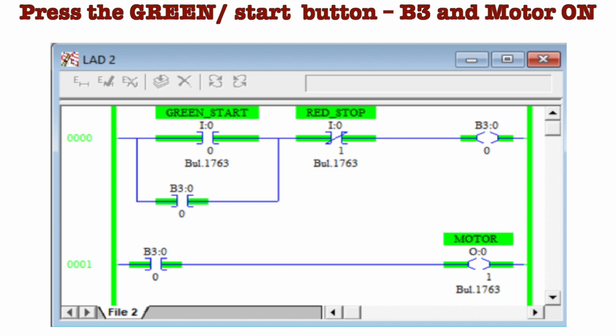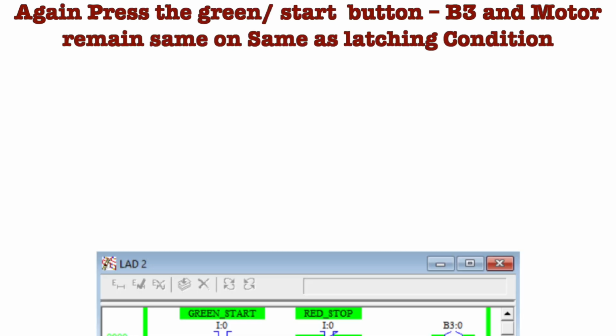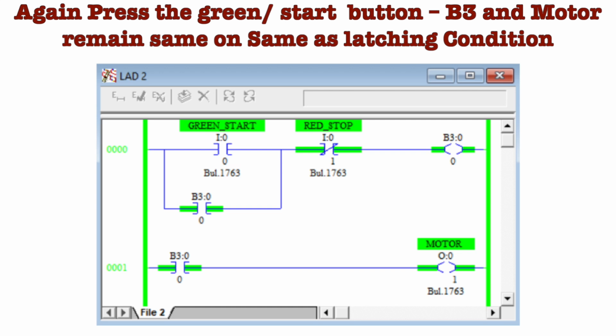So the B3 switch connected in parallel with the green button will also go high, and the one connected with the output will also go high. So we get a high B3 and your motor will turn on. Now when you press the green button again or change its state, there will be no effect. Your B3 and motor will remain on. This condition is called a latching condition.